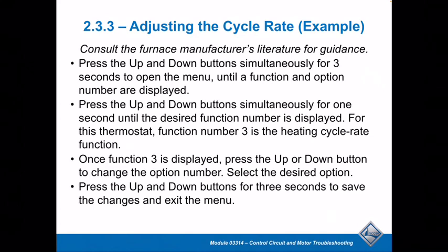I've had appliances that were very, very oversized in applications, and the fix or the best remedy that I can do without replacing the unit was to put an electronic thermostat and adjust the cycle rate to try to help control that.